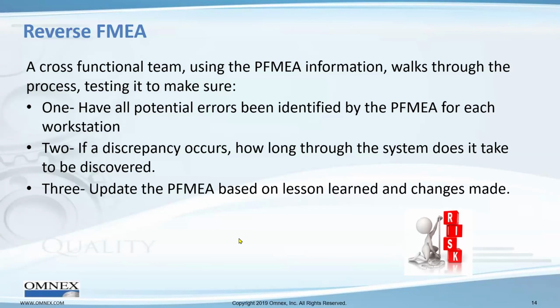Now, once we've gone through and evaluated the system and our occurrence and detection, we may update our PFMEA. We also might identify additional failure modes, which then will result in additional lines in the PFMEA.